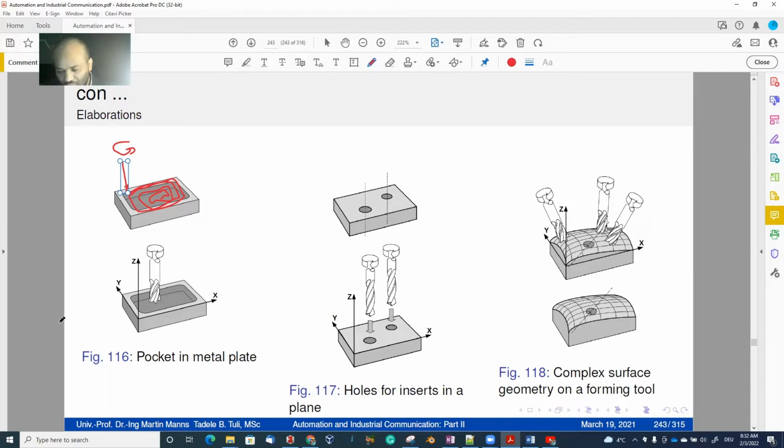As I have to repeat again, the axis of rotation of the tool is always assigned to the z-axis, the longer one will be assigned to the x-axis, and the shorter one to the y-axis. The same thing applies whenever we do these operations. Sometimes, assume you are cutting a turbine blade, or pump impeller blades.